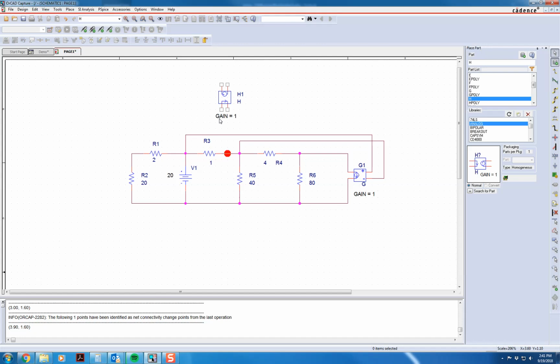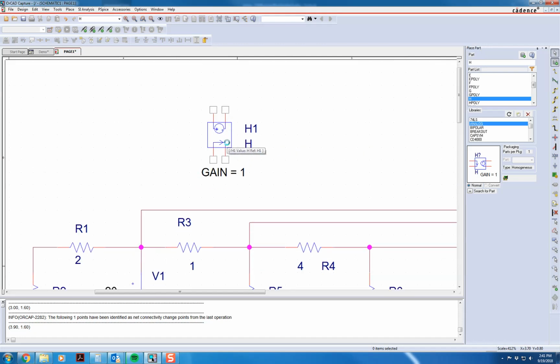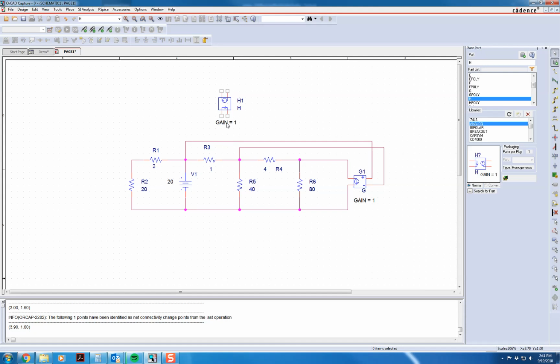And I'm going to hit escape for now so we can see. Okay, great. The issue we have here, we're going to have to actually delete some things from this circuit to make this work. The current is going through this 40 ohm resistor. So I've got to wire this up in series, current and same. So I'm going to actually delete that little wire right here,